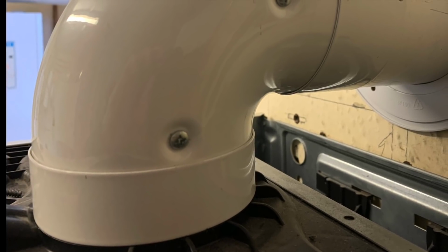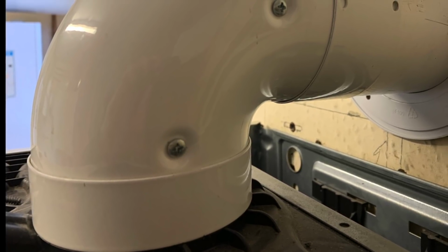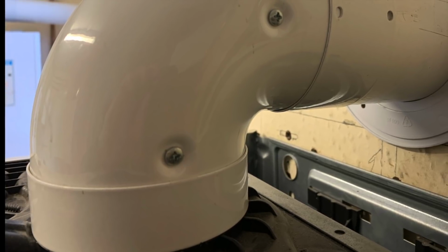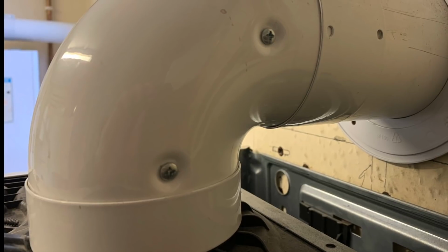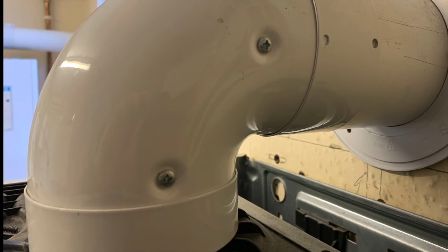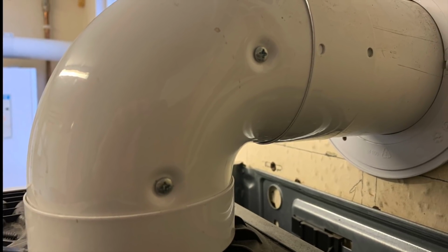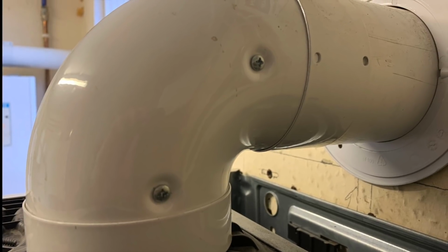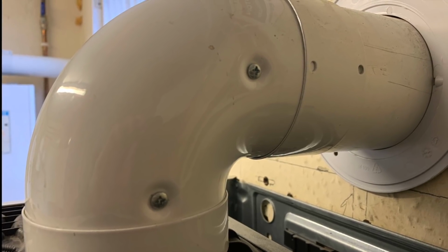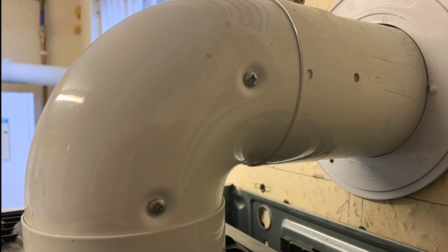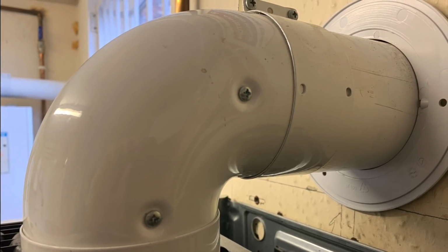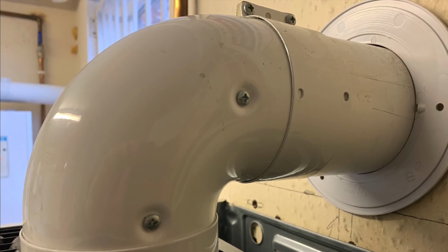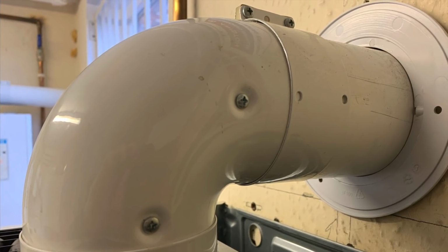Now, this flue system looks a lot like the Vaillant flue, but it's actually off an Ariston boiler, and this does not require screwing, but it still requires the 2 collars. And if you look at the collar which joins the flue elbow to the actual main flue system, it's got 2 holes in it, but the holes are not for screws, they're viewports to check that you've gone full socket with the flue system. So again guys, not every flue requires screws. You just need to read the manufacturer's instructions.